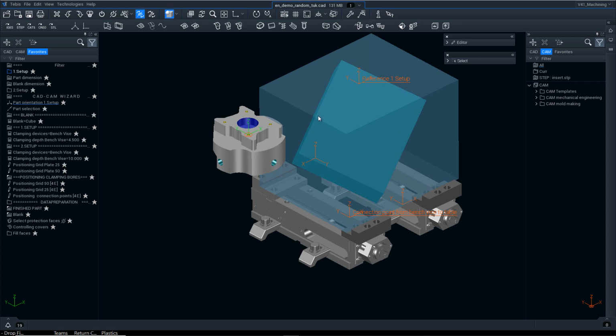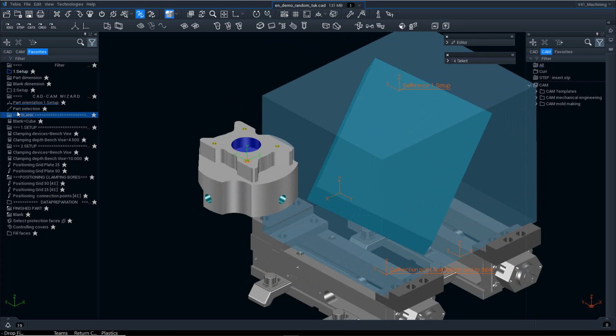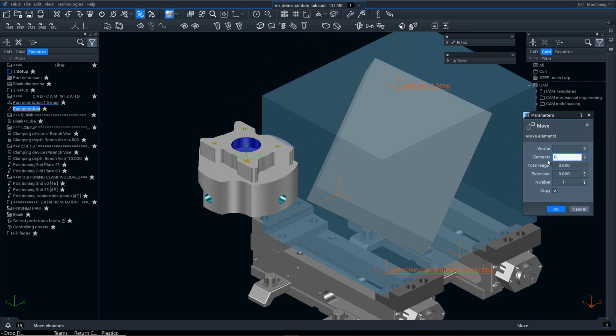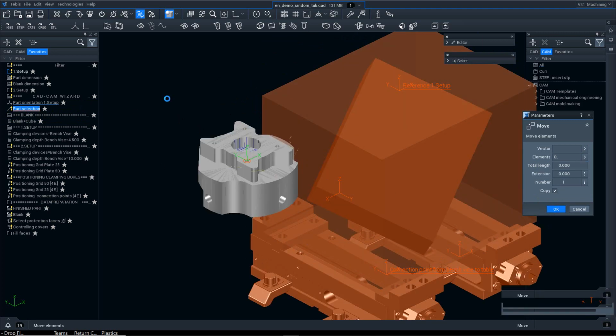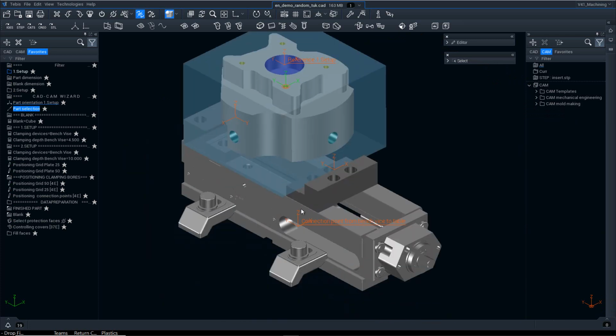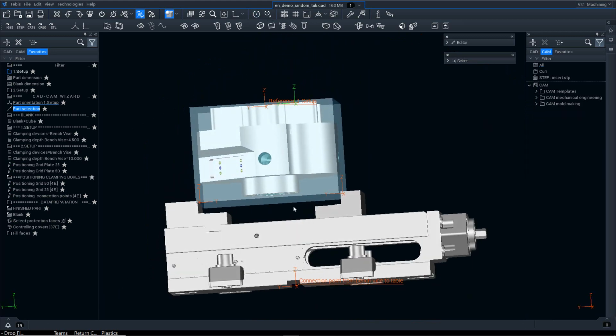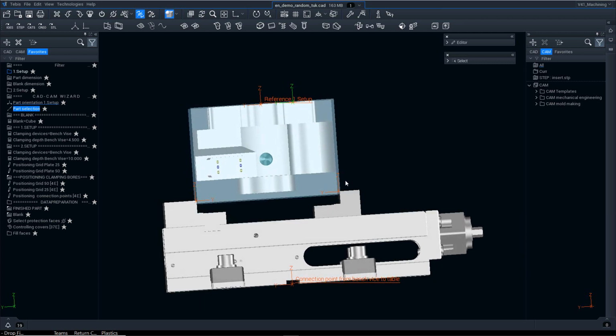Now what we need to do is exchange now the template data for the data which we actually want to machine, and we'll just select the data we want to machine now and apply this. And again, the structure will update with the blank and the clamping devices to the new data now. And there you see, we're now back to 1 clamp. We have our blank, which has been produced around the size of the model with some excess. And you'll see in here that the clamp has been applied not only with the right orientation, but to the right clamping position on the part.